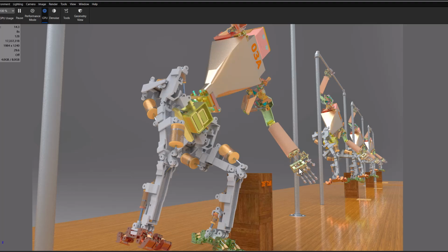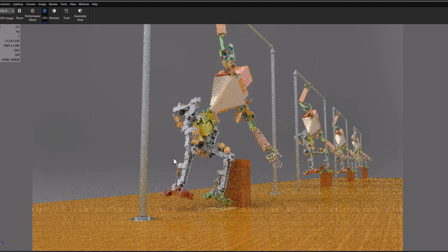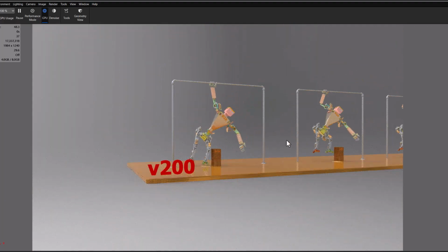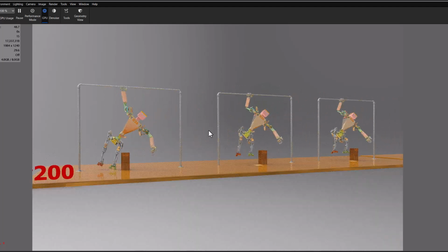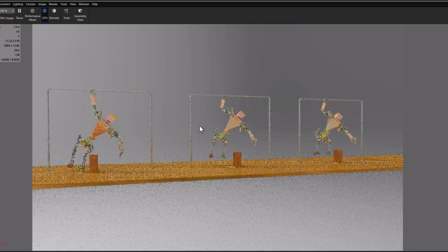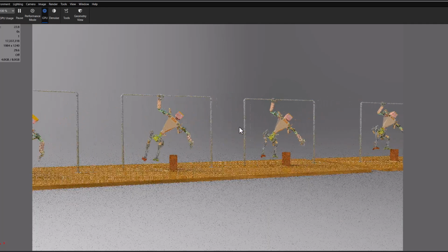And of course, over here is the hand all straightened out. And this is the issue that I've been working on. You can see here the robot just flexed its legs, it flexed its hips and knees, and that lifts the feet off the ground by an inch or two. And then the robot started abducting its right arm, and that lifts it up. And this is just a drawing showing how that works.